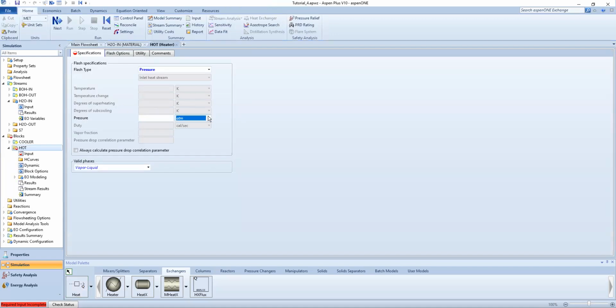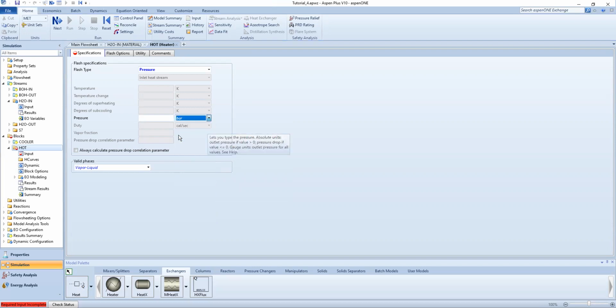And the first degree of freedom, I'm just going to specify it now. Basically the pressure drop will be 0 in this case. So let me go to bar. And 0 here. And as you can see, everything is blue. I don't have any red. This yellow diamond basically means that the results have to be updated because we changed the flow sheet, right? And the yellow diamonds will only appear next to the elements we already ran during the last iteration of the simulation, right?